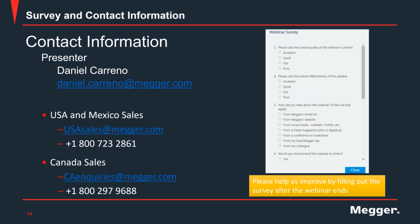All right. Also for you, Sanket, up to what percentage of error can we say that the readings are okay? What are the steps to be taken if error percentages cross that limit? So the same standard that I mentioned in the previous question, C57.12.00, states the tolerance for the ratio limits as 0.5%, and that 0.5% is with respect to the nameplate values, and that's the default limit that's set in the software as well.